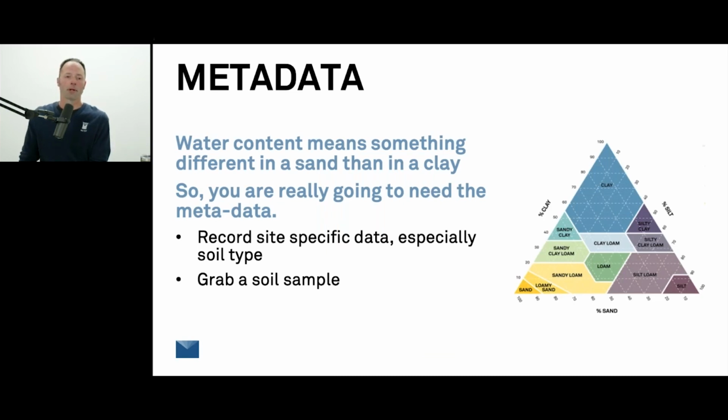Number one thing to remember, get good soil to sensor contact. The number two thing to remember, get good soil to sensor contact, and you're probably going to be fine.